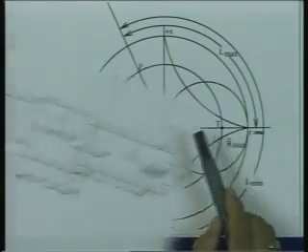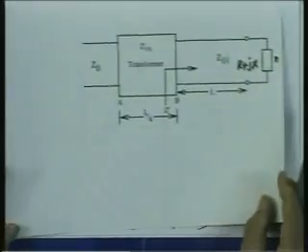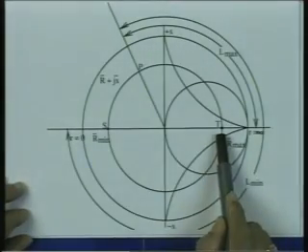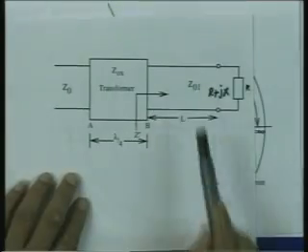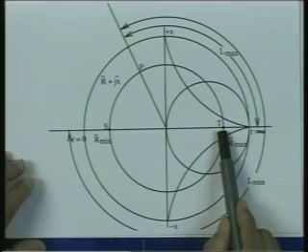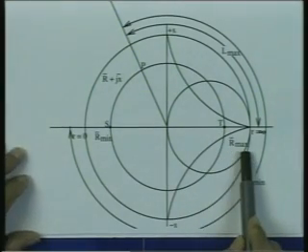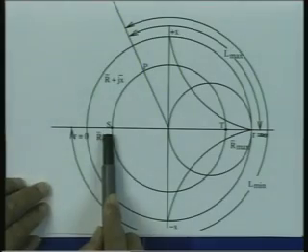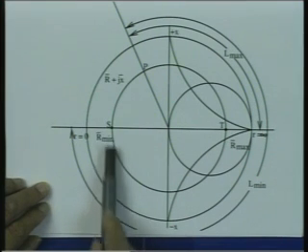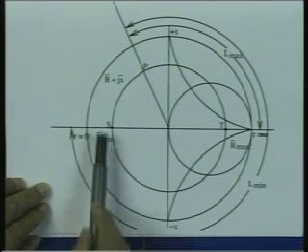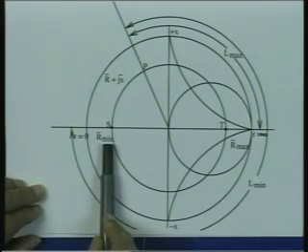So, let us say the VSWR, which is created on this, is given by some rho. The value corresponding to this point T will be Z01, which is the characteristic impedance of this line, multiplied by the VSWR. So, the impedance at this location, which is R max, will be equal to Z01 times the VSWR. Similarly, if I go to a point here S, which gives you the minimum resistance, its value will be the R min, and that will be equal to Z01 divided by the VSWR.